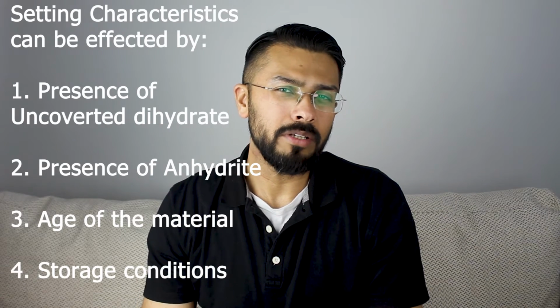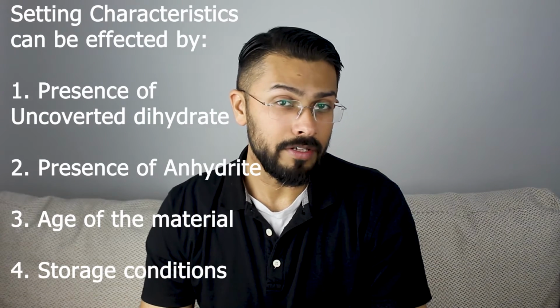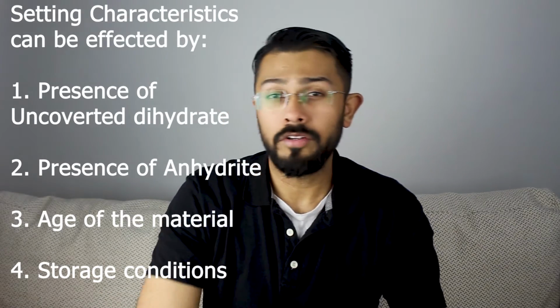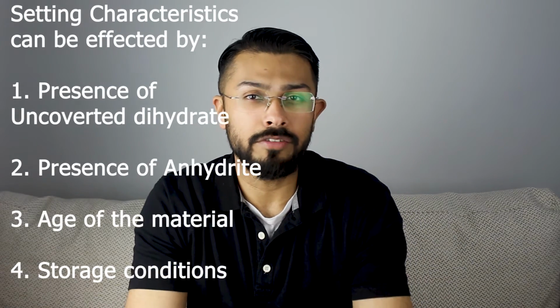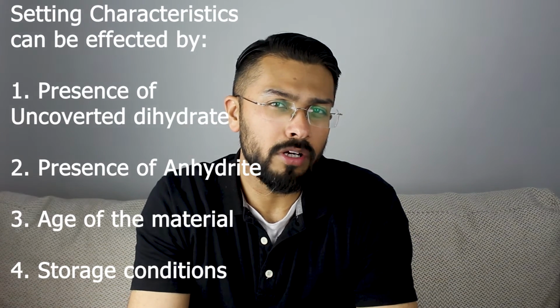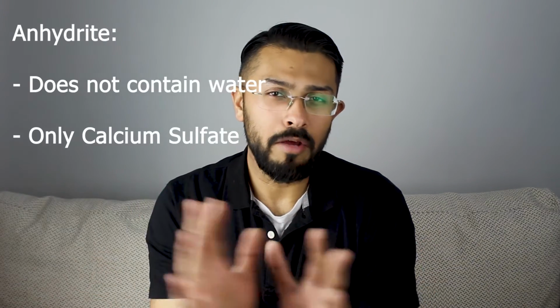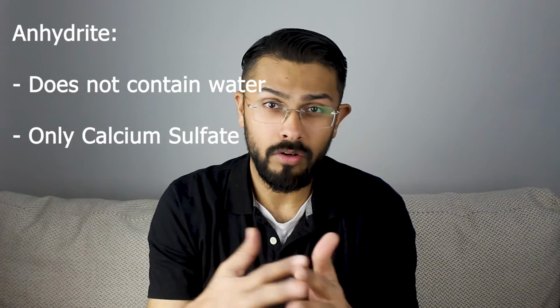The setting characteristics of gypsum products can be affected not only by the presence of unconverted dihydrate but also by the presence of anhydrite, the age of the material, and the storage conditions experienced by the material prior to use. Small quantities of unconverted dihydrate act as centers for nucleation, as we discussed earlier. Anhydrite reacts very rapidly with water, producing a marked acceleration in setting. Just to let you know, anhydrite is the form of gypsum that does not have water, so it's only calcium sulfate. That's it, without hemihydrate or dihydrate.